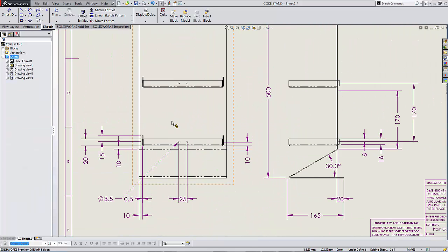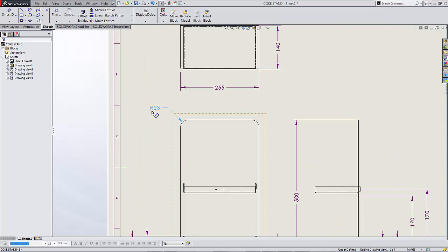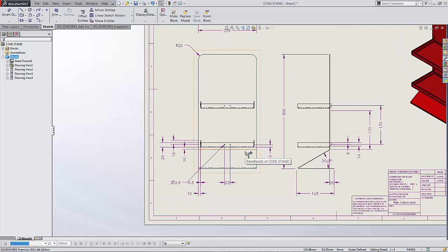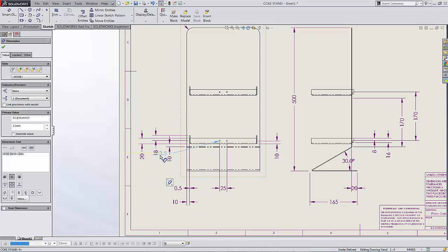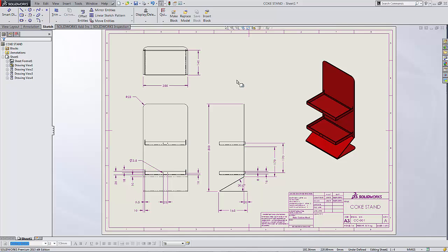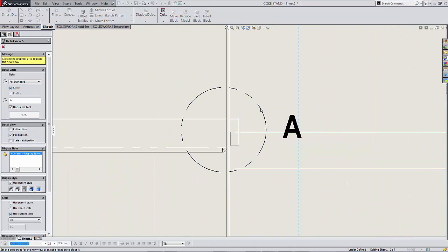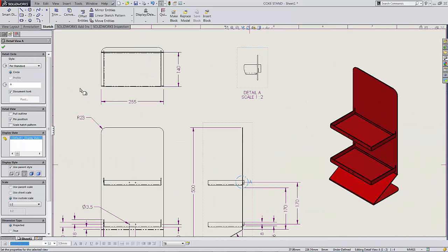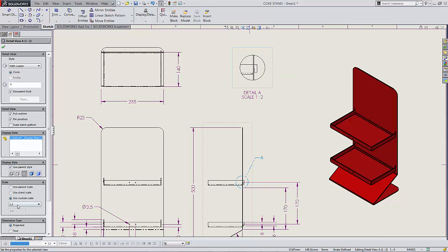Certainly nowadays if I'm giving a metal basher or a sheet metal guy a technical drawing, I generally just give them the DXF file and you can work from that. I just put a couple of dimensions on there just to give them an idea of the scale. But again, you can see how easy it is just to kind of move things around and place them wherever we want to. Also, we can do things like detail views and add detail views as well really quickly. So maybe a detail view of that little tab over here, and we'll just add a leader on there, just give it a full outline as well. And again, I can change the scale of that if I wanted to say 1 to 1.